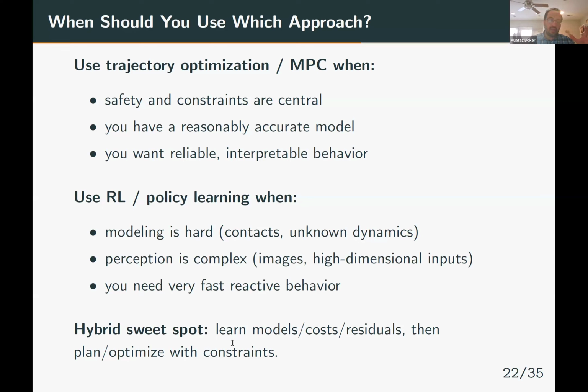There is also another emerging technique called Koopman modeling, where you come up with a linear model of a nonlinear system using data, and then you solve a model predictive control or an LQR control based on that model. So there are hybrid approaches that one can also consider.